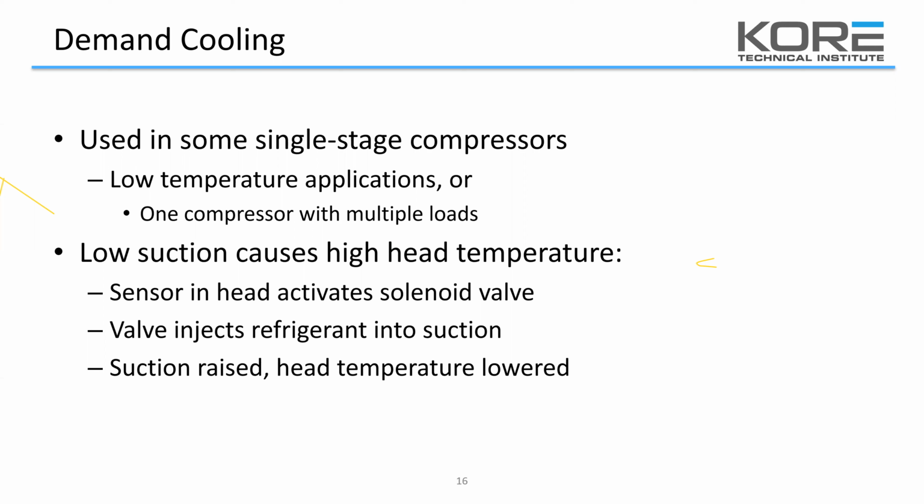Well, what we have is what we call demand cooling, and it's used on some single stage compressors, but for the low temperature applications where you got one compressor and a few different loads, and with that low suction and where our high head temperatures we're going to get, we put a sensor inside of the cylinder head that is going to activate a solenoid valve. That solenoid valve is going to inject refrigerant into the suction line of the compressor and thus increase its mass flow and lower the temperature.